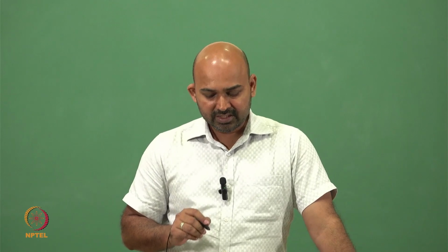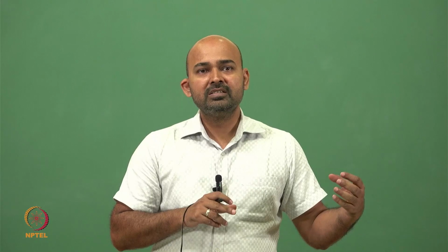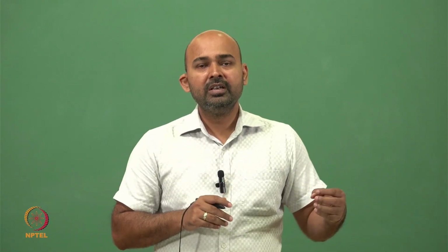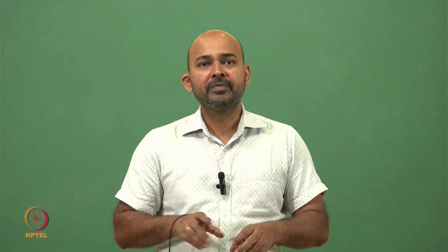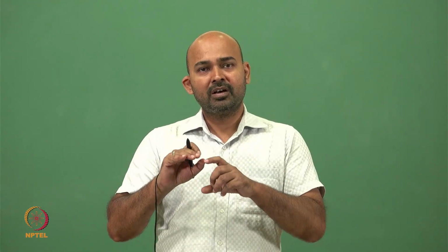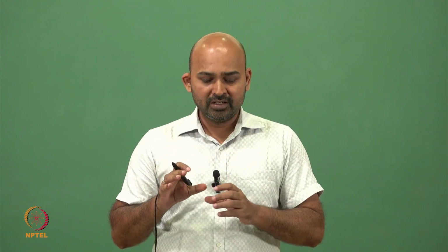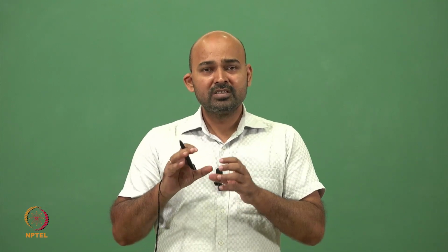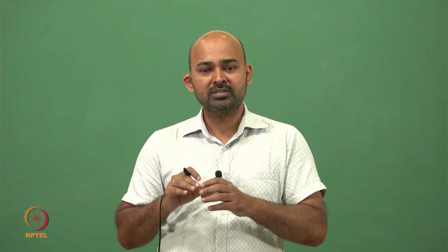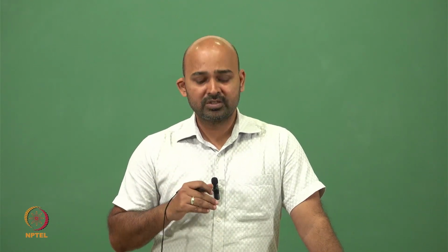This is the amplifier stage. Now this amplifier does not know whether the signal is with noise or without noise. Whatever comes in at the V sensor node will be amplified using this circuit, and the V out will have an amplified output along with the noise. If noise is there, that noise also gets amplified. This amplified noise is the problem because we cannot send this noise also to the controllers, otherwise they cannot detect whether it's a signal or it's noise.